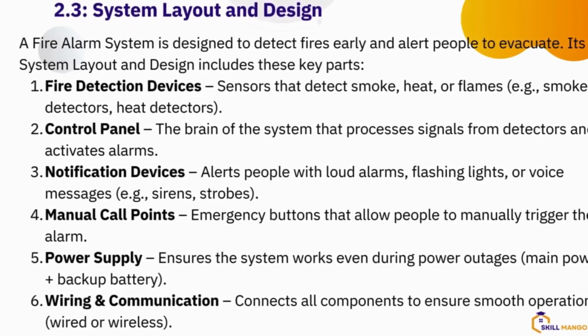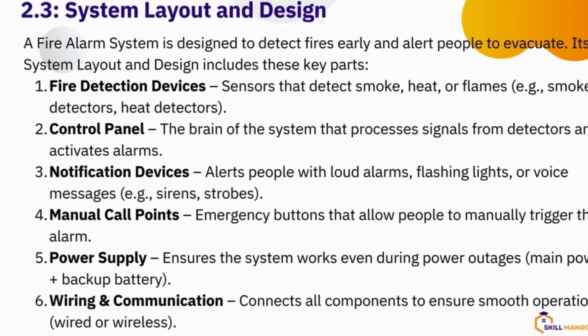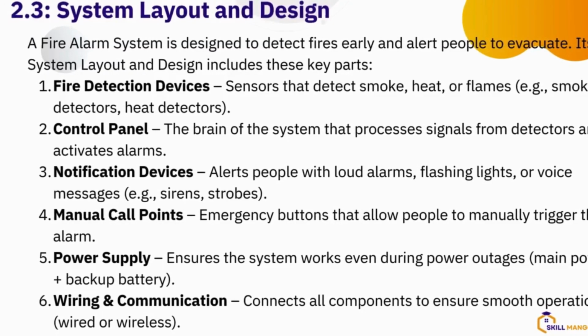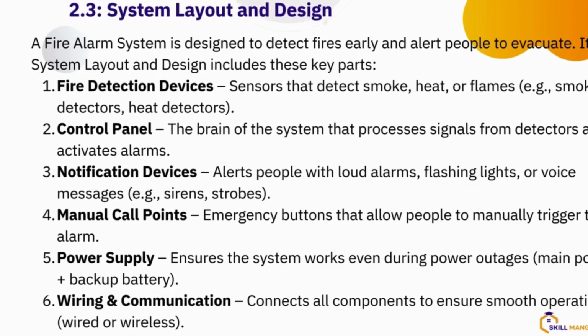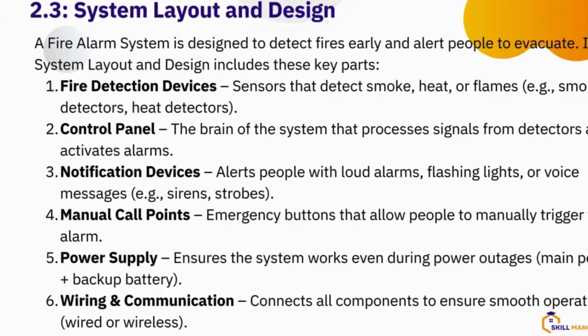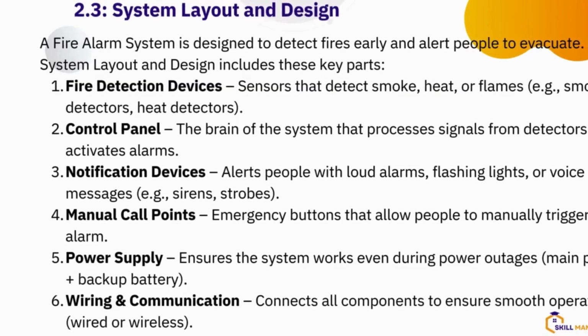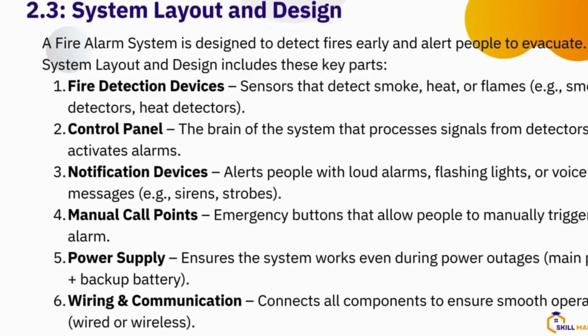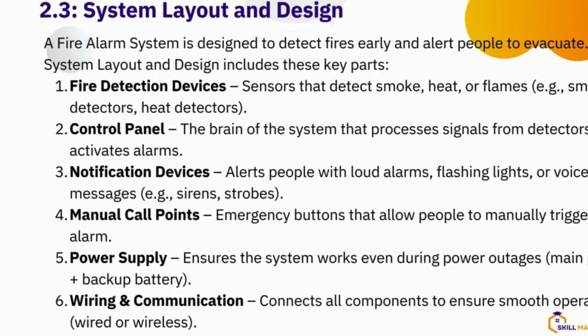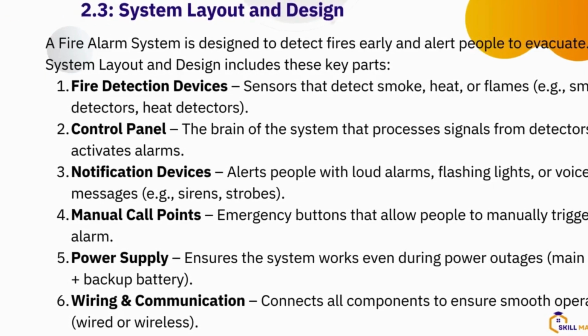Then you now check your cable route and see how to route your cable. Then how to connect and the position to place your manual call point (MCP) or the sounder flasher in each of the zones or loop. You have to understand all these devices. You have to count thoroughly.